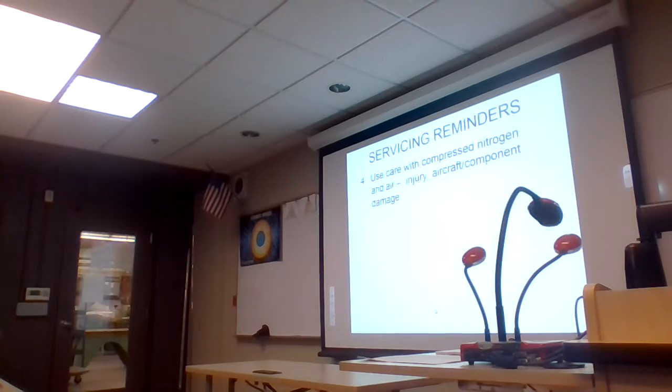Use care with compressed air and nitrogen. We use compressed air sometimes for servicing purposes, same thing with nitrogen. But I prefer not to use shop air to clean anything off. When you're blowing debris, the debris ends up going someplace, probably in the aircraft. So I prefer to use a vacuum if I can. And nitrogen is probably the more preferred gas that we use for servicing.